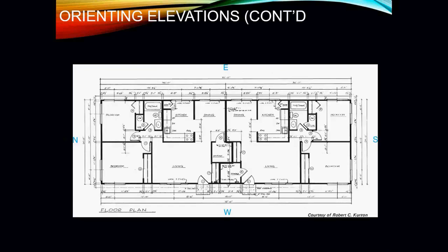This is another more in-depth look. In fact, this is a complete floor plan. As it tells you, all of the rooms are labeled. It gives you the location of your bathtubs, your toilets, your sinks. It gives you your closets, all aspects of the actual interior construction of the home is shown on your floor plans here.